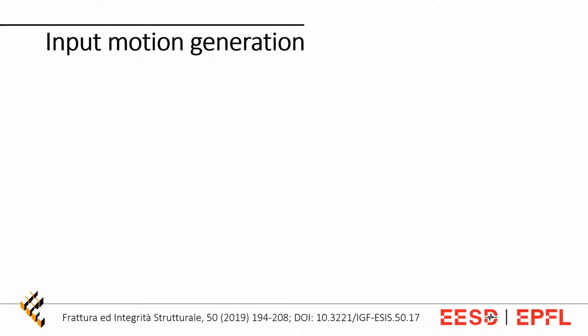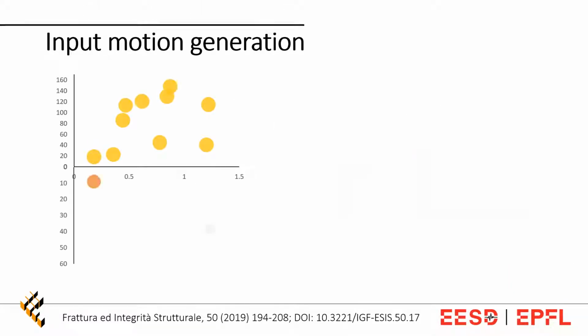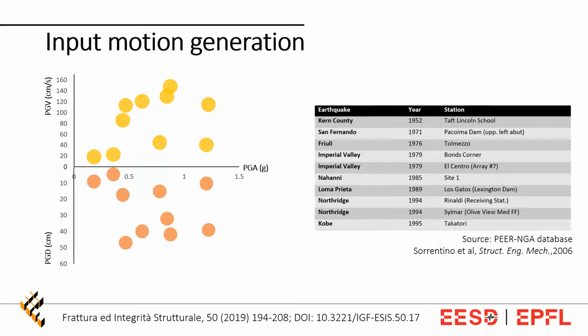For the study, 10 natural ground motions covering a wide range of ground properties are selected. From these ground motions, artificial input motions for the wall supports are generated by using signal processing techniques. Of these motions, we control the difference in phase and in amplitude.